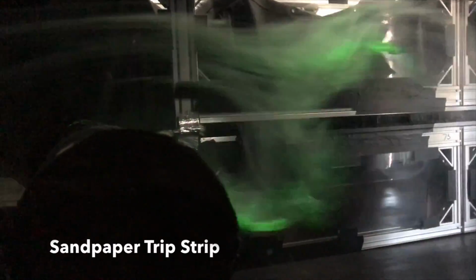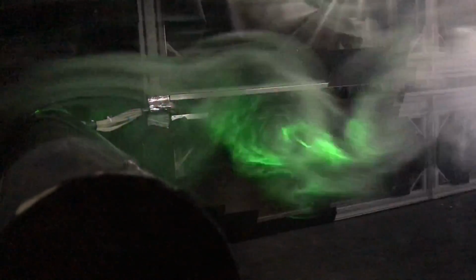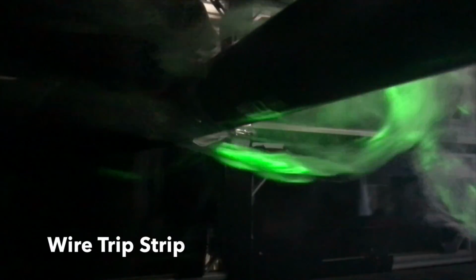A trip strip or a surface perturbation can be added to the cylinder. This will cause the boundary layer to prematurely transition from laminar flow to turbulent. To do this, a thin sheet of sandpaper, then a wire, was placed at a location before the natural separation location of the flow on the surface of the cylinder. At lower Reynolds numbers, the wire was more effective at delaying separation of the flow. This reduced the pressure drag on the cylinder significantly compared to the sandpaper.